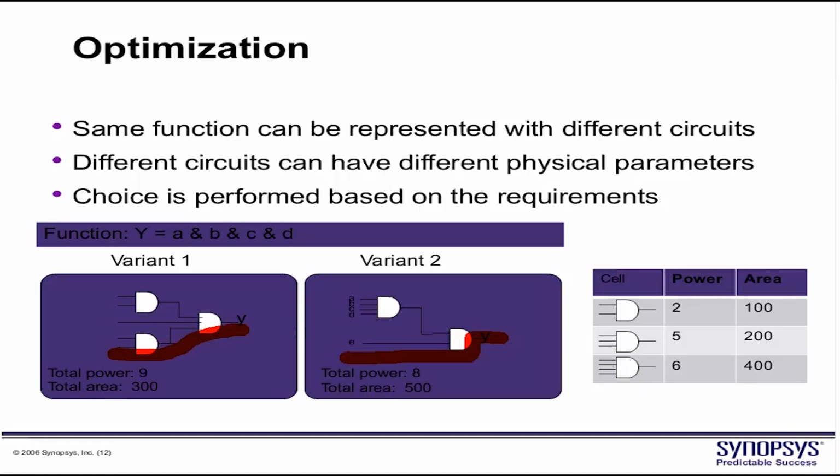It does not mean that gates which have a number of inputs higher than 2 or 3 are undesirable. That will again depend on our delay requirements. So let's say a 3 input AND gate, the delay from input 1 to output, from input 2 to output, from input 3 to output, all will be similar in nature.